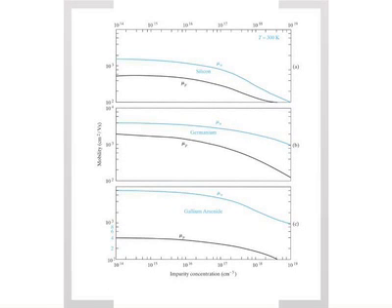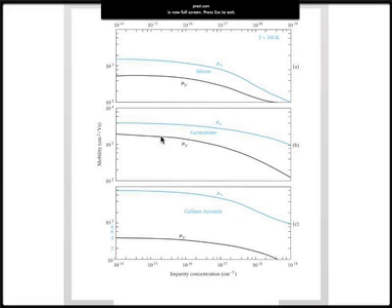The next important parameter that impacts mobility is the concentration of donors or acceptors, impurities. As we saw in our temperature graph, impurity scattering tends to be important at low temperatures, not at very high temperatures. But even at room temperature, if you increase the impurity concentration, there will be more scattering that happens. That's common sense, right? If you have more impurities in your lattice, of course, electrons will have higher probability of colliding with them, scattering from them. Indeed, that's what will happen, which is shown in these graphs.